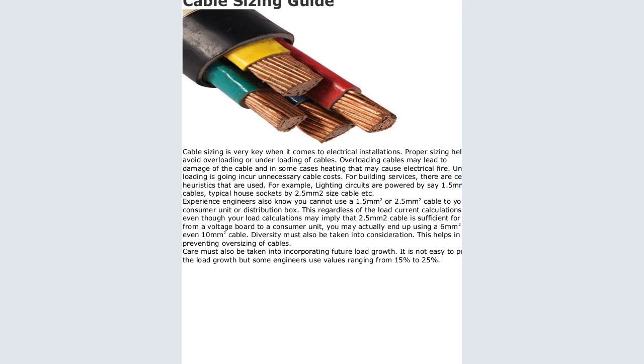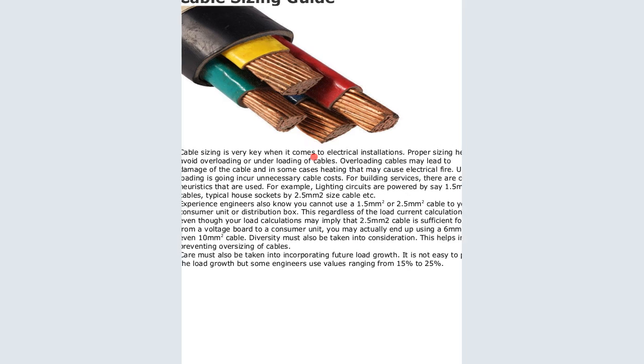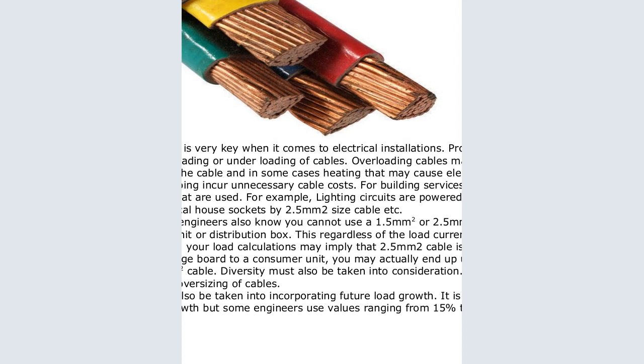If you look keenly into this cable, the width or the diameter of this cable is too thick, so the cable cannot be solid. You remember, we normally have singles and we have stranded. Stranded are these ones that have several strands to make a single conductor, like the live conductor or the neutral conductor. When you look keenly, you see several strands being put together to make one conductor. This is done for possibility to be able to bend the cable.